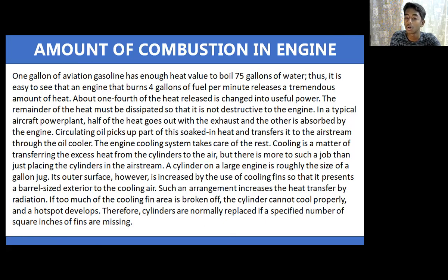A cylinder on a large engine is roughly the size of a gallon jug. Its outer surface, however, is increased by the use of cooling fins so that it presents a barrel-sized exterior to the cooling air. Such an arrangement increases the heat transfer by radiation.